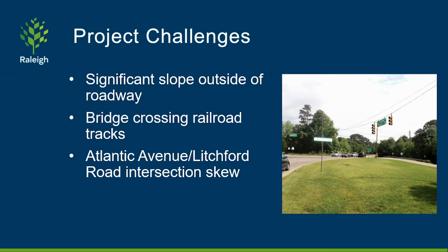The bridge crossing the railroad tracks challenged the design team to meet the needs of multiple users. Additional length of the bridge span to accommodate railroad traffic below the bridge causes an increase in the roadway elevation. There is a potential vertical curvature concern at this location that could impair motorist visibility if the roadway elevation is significantly raised. The design team is tasked with optimizing the bridge design to meet both the railroad and the motorist needs.